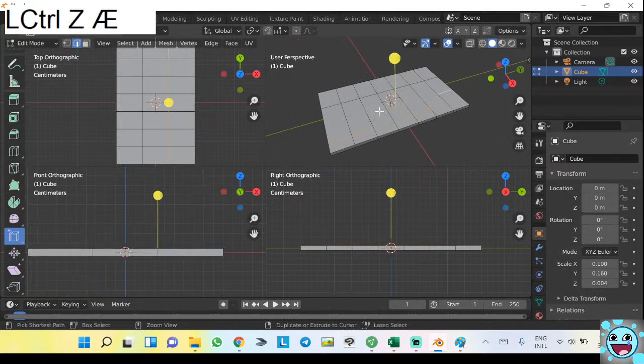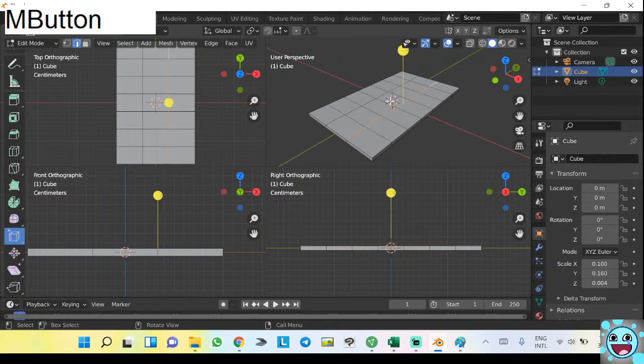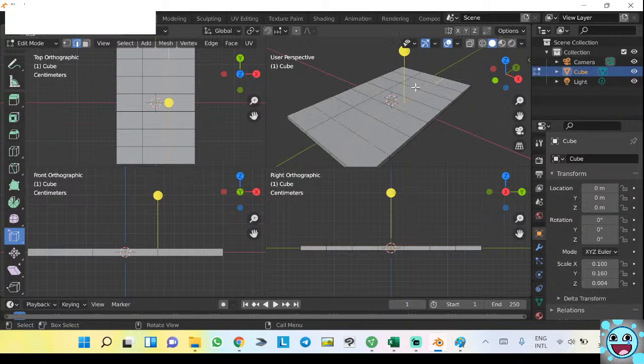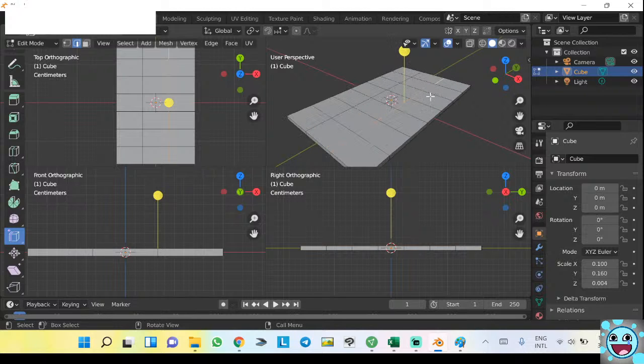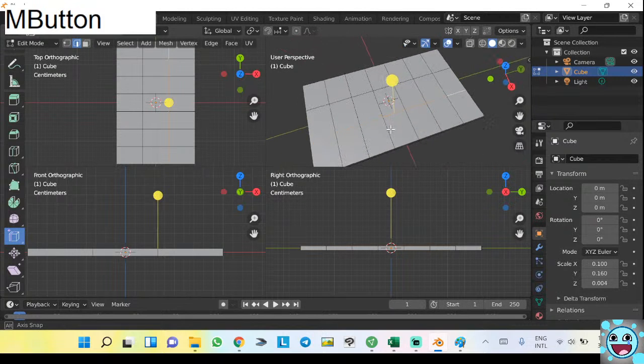Yeah, this one. It seems that we accidentally clicked on extrude the first time we attempted it, so it locks the already formed face. If you are not sure what happened, just undo what you had done. You might have extruded something or done a command that made it impossible.